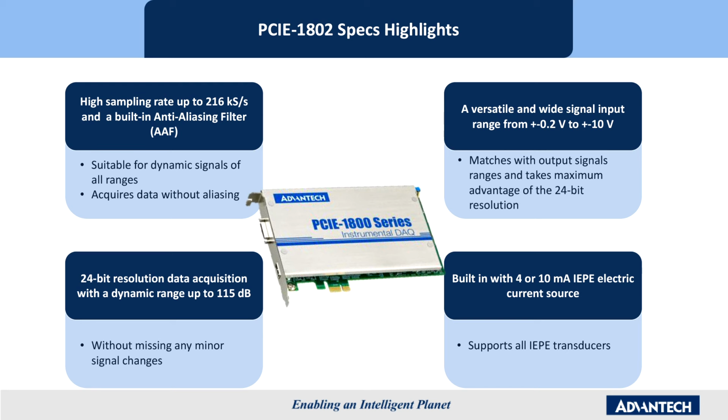The larger the ratio is, the larger the signal range the data acquisition card can measure. The highest signal level is restricted by the signal input range of the data acquisition modules. It cannot be higher than the input range, and the smallest signal level is limited by noise and harmonic wave when the signal level is too small.